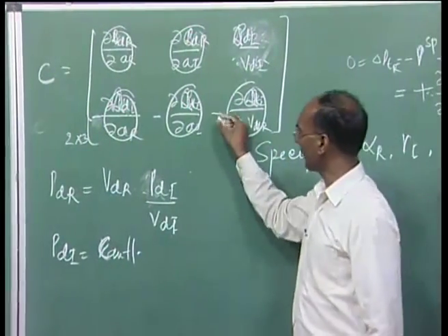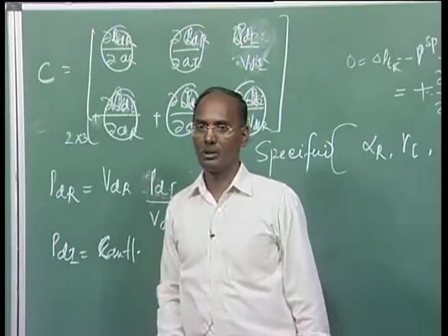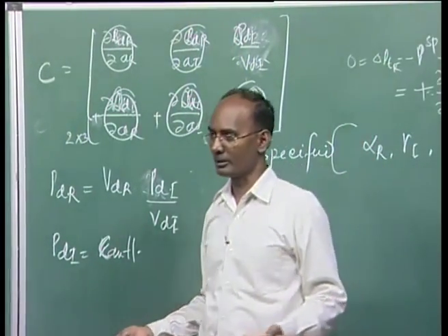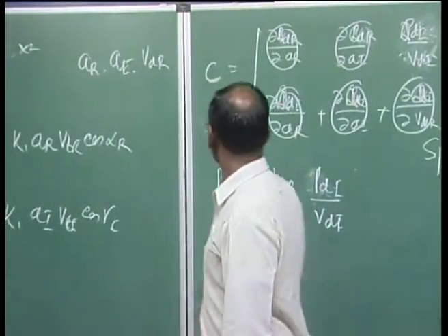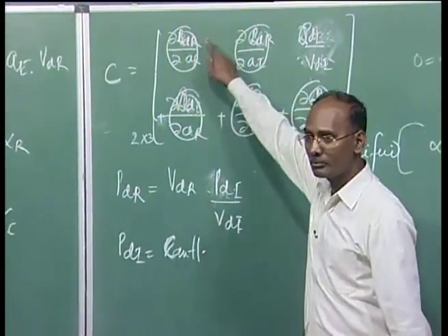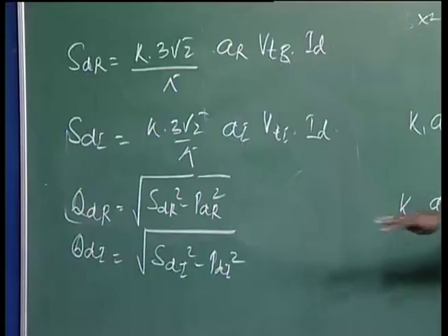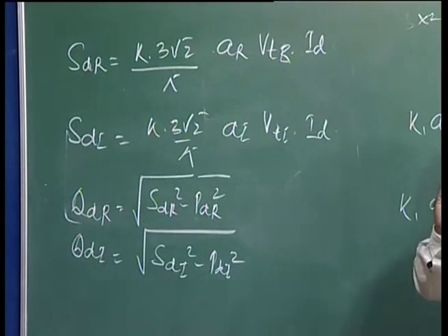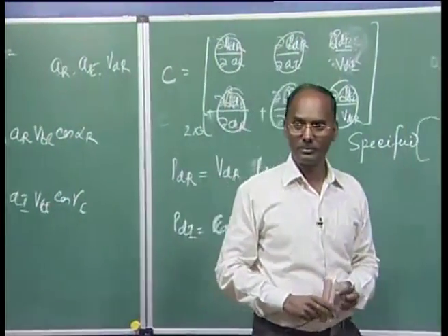Moreover, the sign in this case will be positive, because the Q is taken as a load at both the inverter as well as the rectifier terminal. So, this element you have to derive from this equation and then differentiate it. You are going to get some terms here, it is not 0.